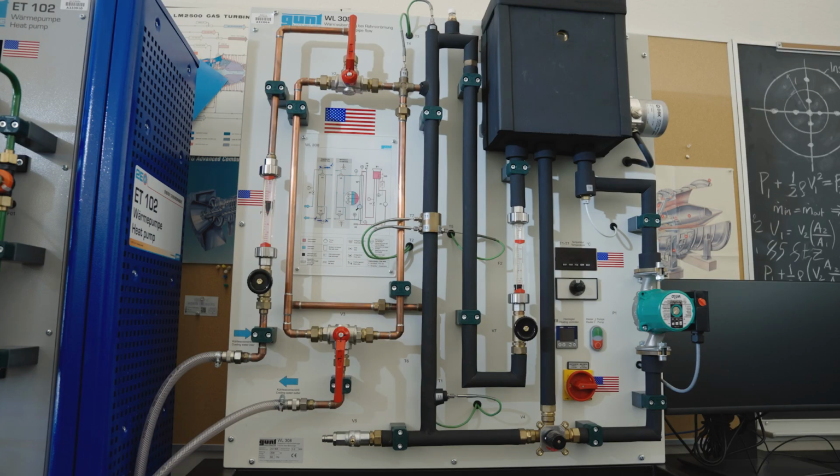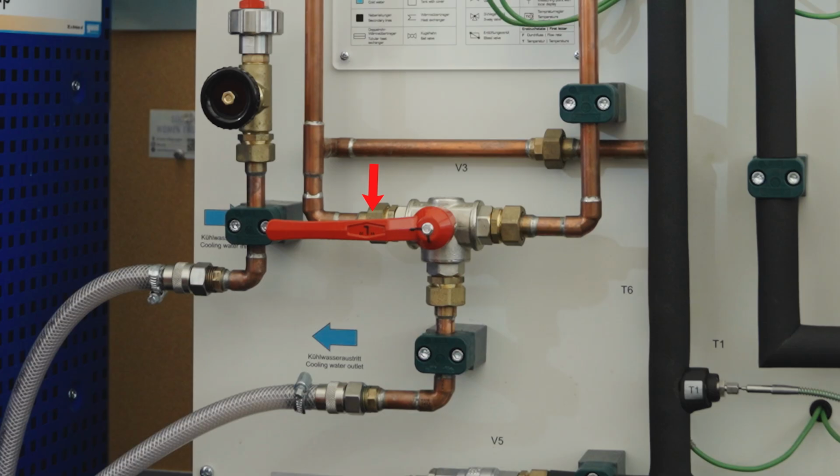In this video, we will describe an experiment in which the heat exchanger is used in parallel and counterflow configurations with various volumetric flow rates. Remember that in this device, parallel flow is achieved by turning the top three-way valve handle vertically up and the bottom handle vertically down. Counterflow is achieved by turning the top handle horizontally right and the bottom handle horizontally left. Note that the flow rates and temperatures depicted in this video may vary from other laboratory activities. Refer to the laboratory guide provided for specific details.